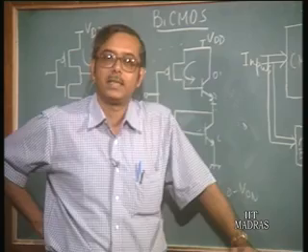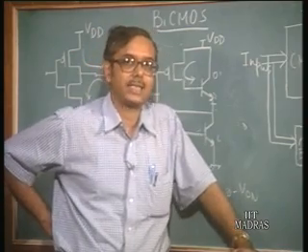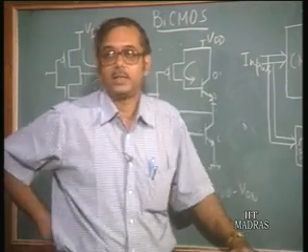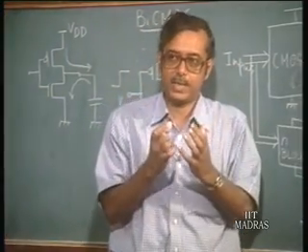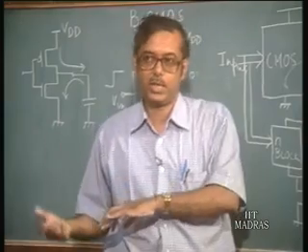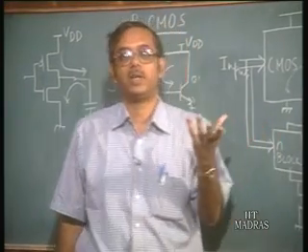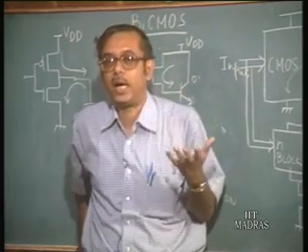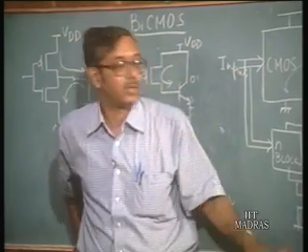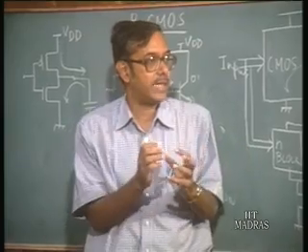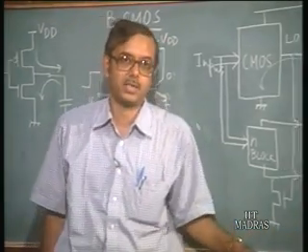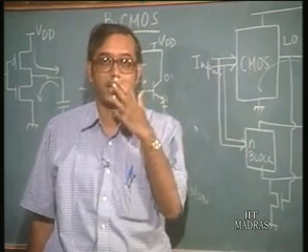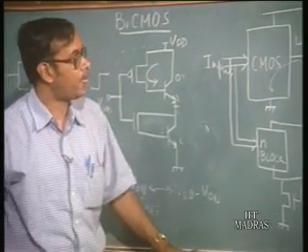in recent days the power supply voltages are being continuously scaled down. There are a lot of reasons for that. One is that as we are going for smaller and smaller devices to improve the speed as well as to reduce the power dissipation, the smaller devices cannot take such high voltages, because the electric fields become too large, with the result that there can be breakdown problems. So, as we reduce the dimension of the device, we must also reduce the power supply voltages. The power supply voltages are also reduced to reduce the power dissipation. So, in order to do that,